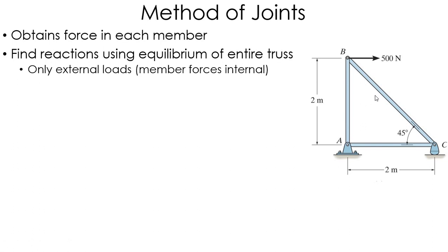And you do that just by summing the forces and summing the moments, using those equilibrium equations for the entire truss that you have here. Okay, and a lot of times this step can be skipped, but it's always good practice to do it, because sometimes you're going to need it. Okay, so find those reactions.